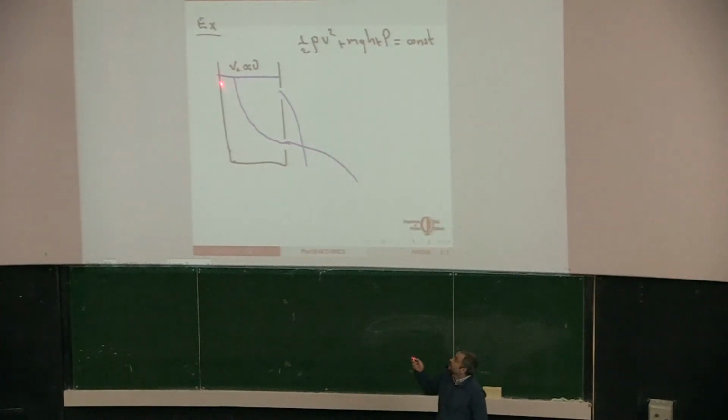The speed of this surface, we can assume that it is very small and ignore it. So we will have some speed V2 over here. Now the pressure at the top of the surface is nothing but atmospheric pressure. So there we have P0. At the opening, the pressure is again the atmospheric pressure. It is open. So here we also have P0.